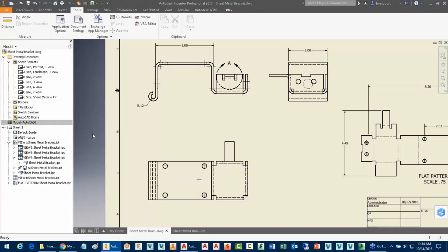So I'm going to do a couple things here. I'm going to use sketch symbols to create a new center of gravity symbol, importing it from AutoCAD. I'm also going to use sketch symbols to house some information about some of the standard notes that we might have on a drawing. So I'll go through that process now. I'll just simply right-click on the sketch symbol heading. There are no contents in here currently. It's just empty. And then I can define a new symbol.